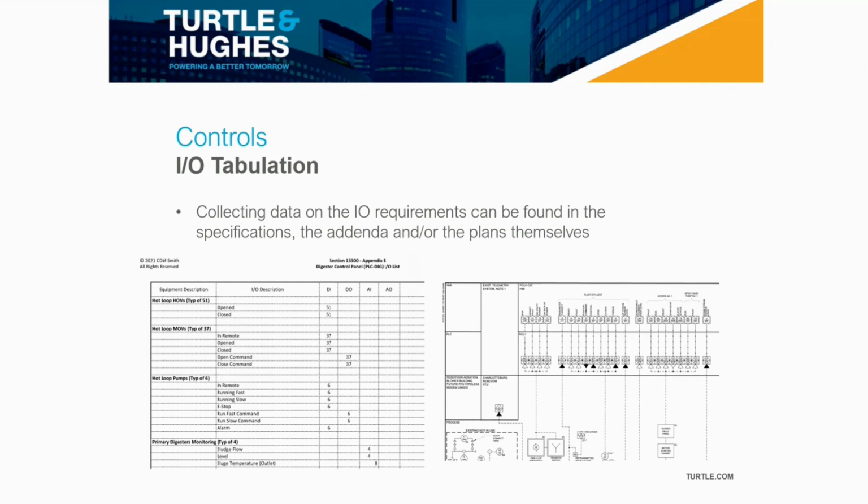One of the things I tell you that you need to be aware of when you're looking at those drawings is they may show a block of I/O, and then in fine print above it, it'll say something like typical for 4. So if you are trying to go through the drawings to add up the I/O, just be aware that they may have either on the drawing or in the notes on the drawing page how many of those type you should be counting.